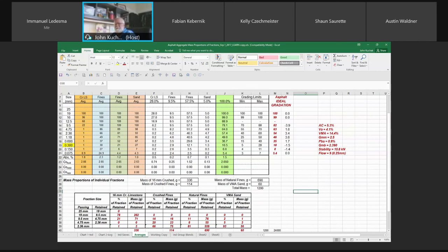Typically, you look at the Asphalt Institute or a lot of the other testing specifications across the States and in Canada, and it's usually 19 millimeter top size maximum. And then 95 to 100 passing the 16 or the 12.5, whatever. So it tells you you got 5% oversize allowed, or you can have it all passing, 95 to 100, whatever.